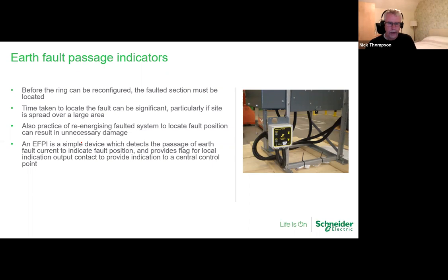And what we mean by re-stressing is that you're stressing all the components in that faulty area: the cables, the switchgear, and more importantly, your feed circuit breaker. When you start to look at feed circuit breakers, you've got to take into account the life of the circuit breaker, and that's not the design life. We're talking about its operational life, not the mechanical endurance of it. We're talking about the number of full fault interruptions it's capable of doing.